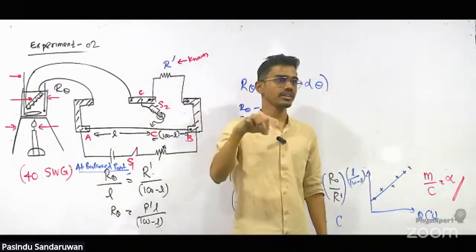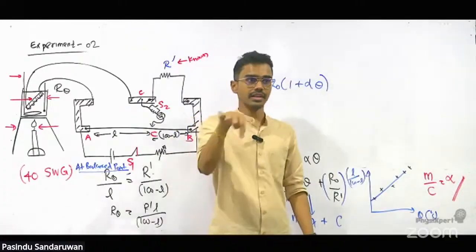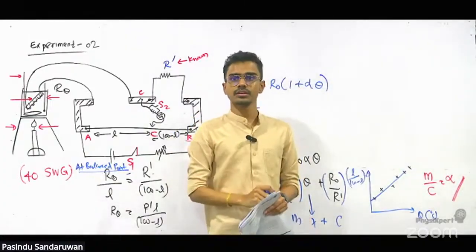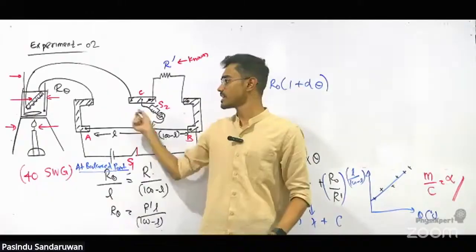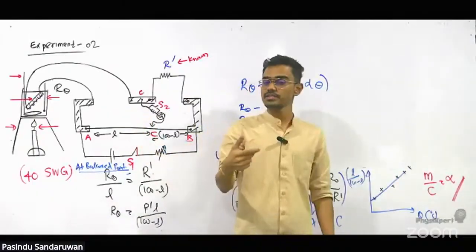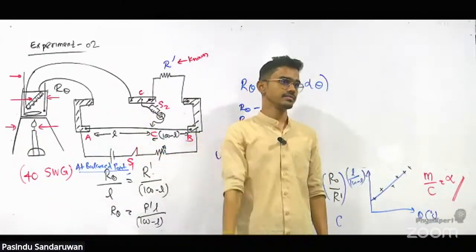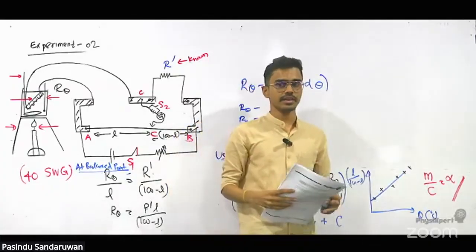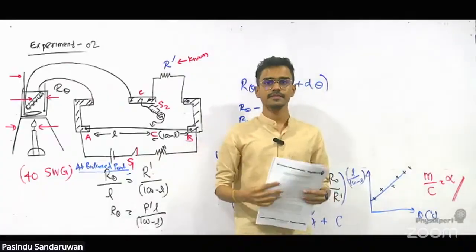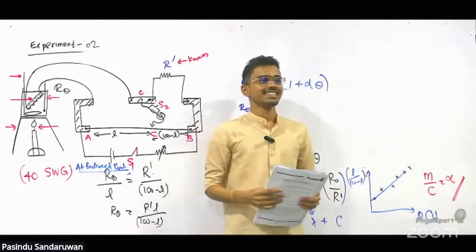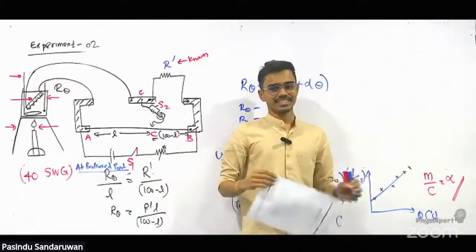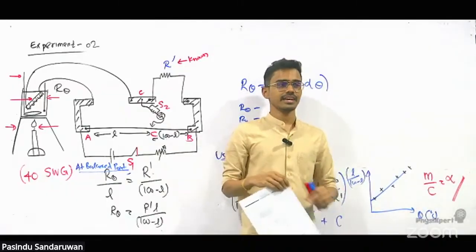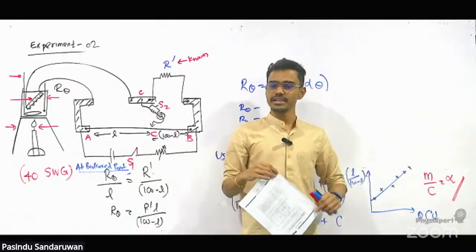Once the rough balance point is known, you know around which length you are going to obtain the balance point. Otherwise, if a large current passes through the galvanometer, it burns out. It has a small coil inside.